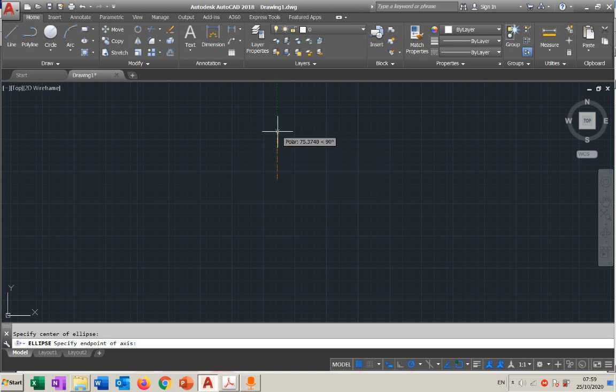Both axes can be true. So we're gonna choose this axis. Now what do we have to do? We have to use the mouse to specify the direction of the axis. Let's say I'm gonna follow the main axis first, then I'll go for the secondary axis. So I'm always following the same procedure so I will remember to not make any mistake.